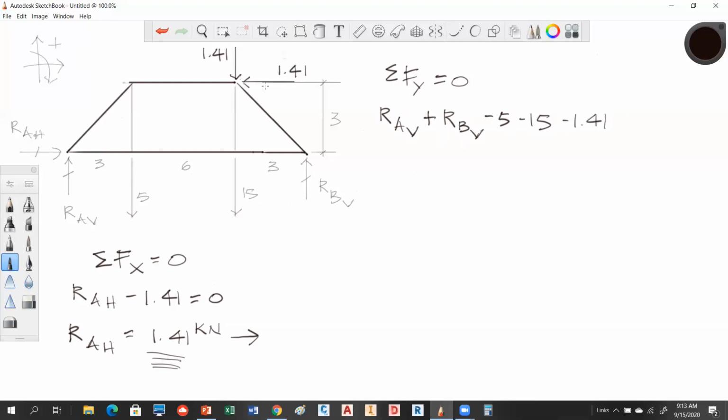Now, here could be a potential pitfall. If when I did these breakdowns I put this in the wrong direction, if I put him up, I've blown that problem. So you really have to watch that when you're doing those vectors. Make sure that when you break your vector down, you're putting it in the right directions, okay? So everybody agree with what I got? I got these guys down, negative, negative, negative, and then these are up. So I think that takes care of all of the vertical components. So this will give us not an answer, but a partial answer.